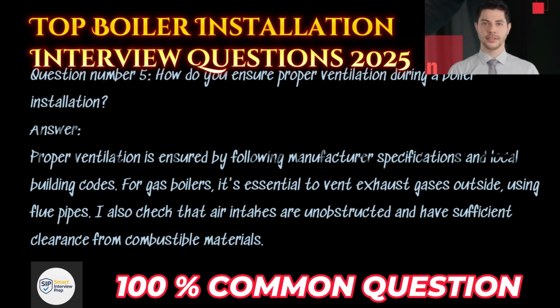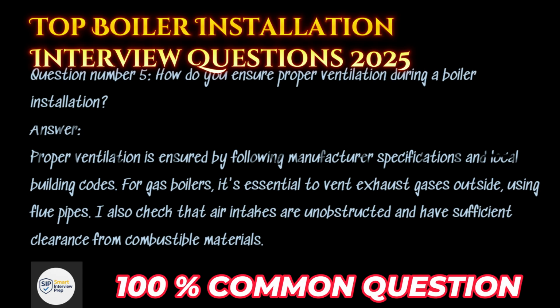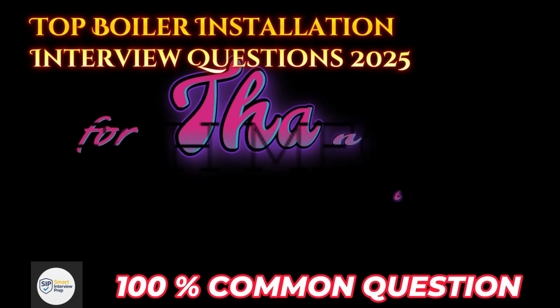Question number 5. How do you ensure proper ventilation during a boiler installation? Answer. Proper ventilation is ensured by following manufacturer specifications and local building codes. It's essential to vent exhaust gases outside for gas boilers, using flue pipes. I also check that air intakes are unobstructed and have sufficient clearance from combustible materials.